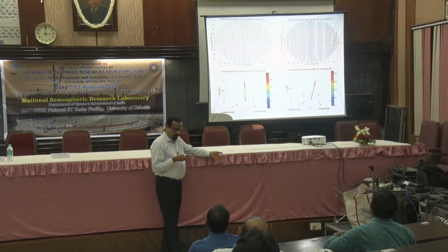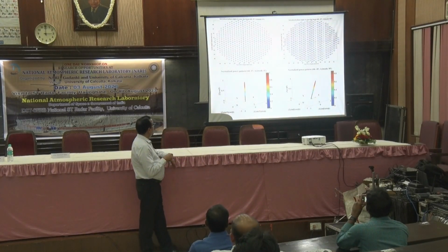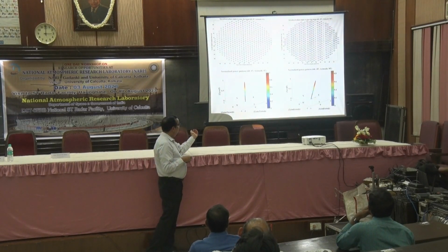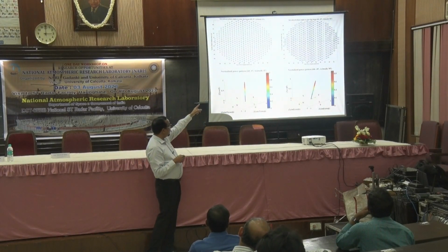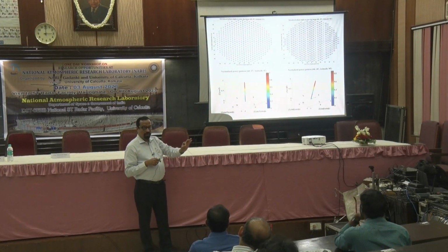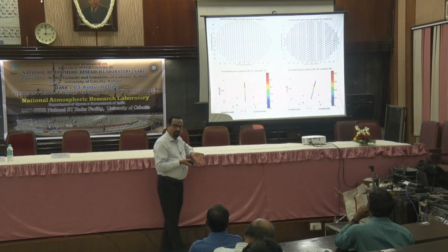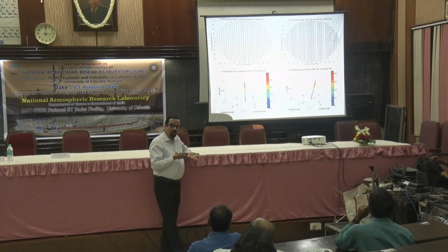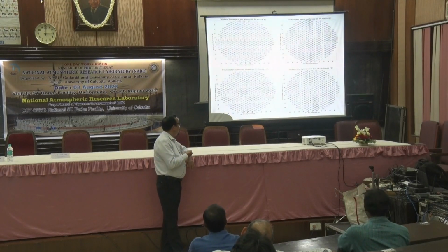So what we do, when each element is given a 0 degree phase, you can see a vertical beam. Now if I tilt it a little bit, 30 degrees away from the vertical, by putting in the phase shifter values, that phase shifter is a digital value for me now. What we have to do is create the beams, or transmit with the vertical beam, and put a receive beam inside the transmit beam, tilted, and I receive the data.